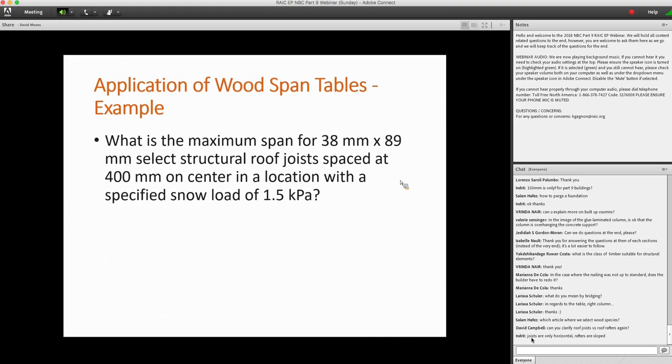And that's what stick frame construction is all about. And those numbers, 2x4 or 2x6, is called the nominal size. It's a name that we give to the size, but it's not actually that big. So when the conversion was made to metric, the decision was made to use the actual dimension. So that's how we have a 38 by 89 as opposed to a 50 by 100. That would have been a 2x4.